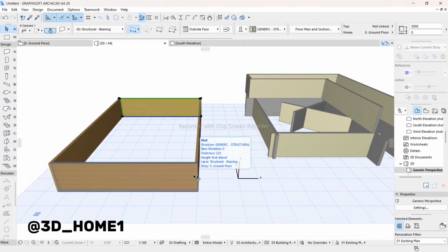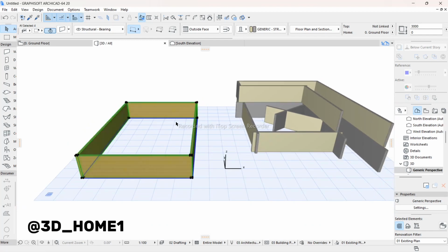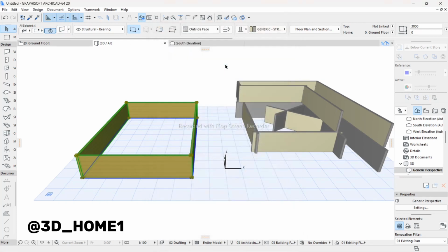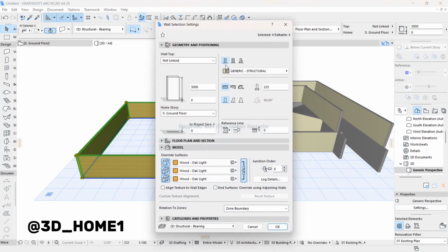Another thing again, if you want to be fast, learn to group. Let's group this one, group everything. Click on shift and select all, then press Ctrl G. So everything has been grouped. So let's go inside. That's on the settings dialog. There's a settings dialog here. If you don't want to press that one, just press Ctrl T, so it will open directly.